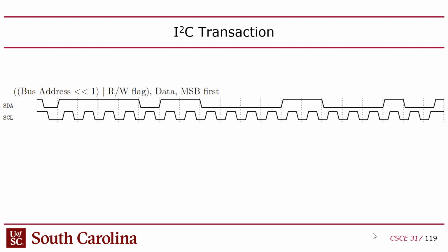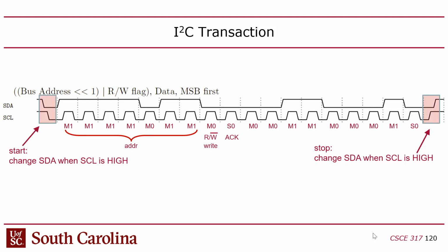So it's going to be 1, 1, 1, 1, 1, 1, 1, 1, 0, and then 1, 1, 0. Right? So I think that's the read or write bit right there. Am I right? Yes. So master sends 1, 1, 1, 1, 0, 1, 1, 0. This is the 9th bit, so that's the read or write.